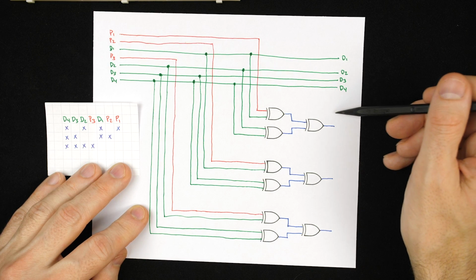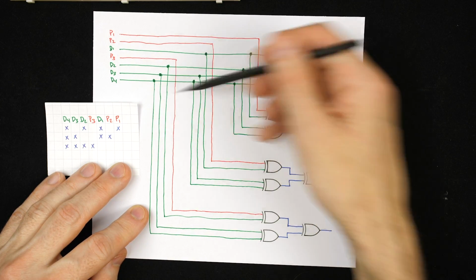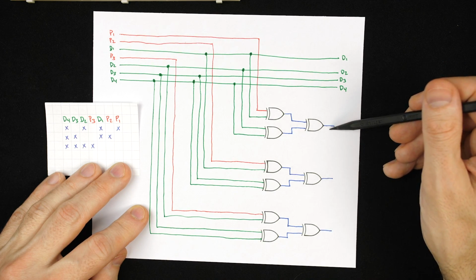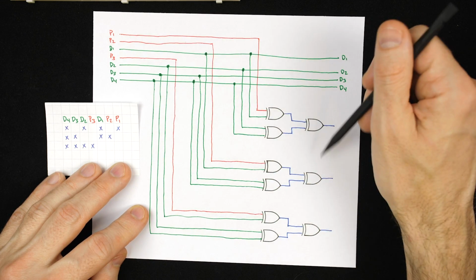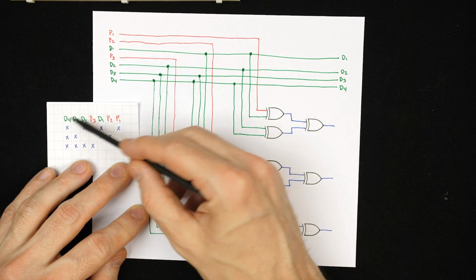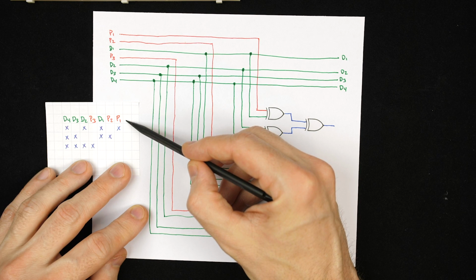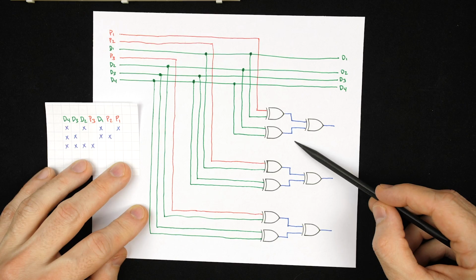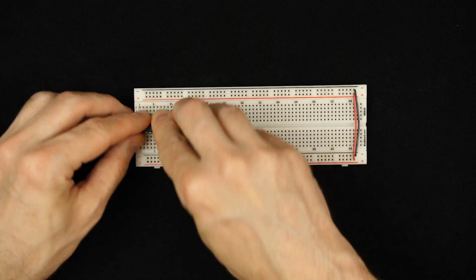And if there hasn't been a bit flipped, then these should all be zeros. But if any of these are a 1, then that means that something has been flipped. And then depending on which combination of them are 1s, well, we can figure out which actual bit exactly was flipped. So let's go ahead and build this, and then we can play with it, and I'll show you exactly how it works. All right, so here we've got some more XOR gates.